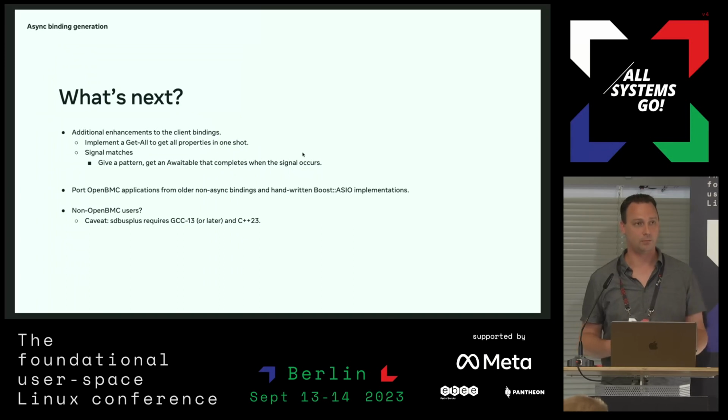If the watchdog isn't poked within the BMC, that will signal the fan controller hardware to say the BMC disappeared, and then the fan controller will usually kick the fans into max speed. So generally, BMCs don't tend to have real-time requirements.